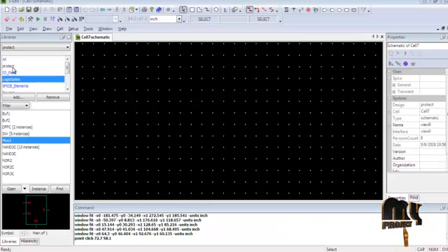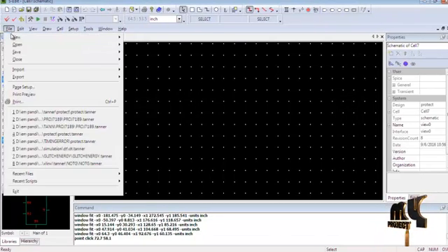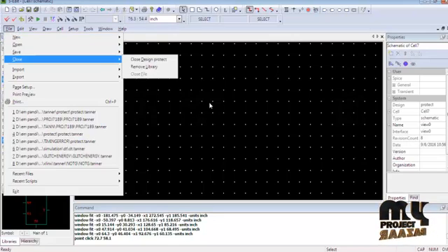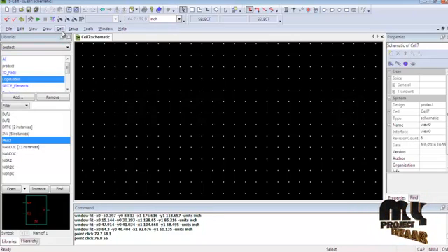Next we see the running process of our product. Our product is done in the Tanner EDA tool. The Tanner EDA tool is a CMOS technology design tool. First we open the S-Edit window. Now the window will open, then select File and create a new design. After creating the new design, we select the cells.